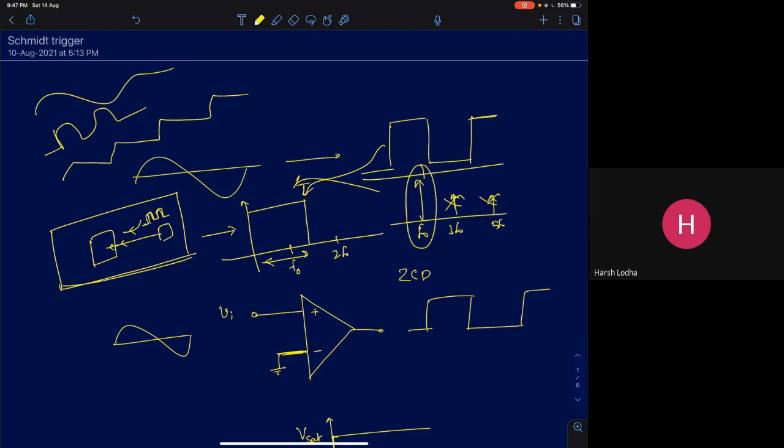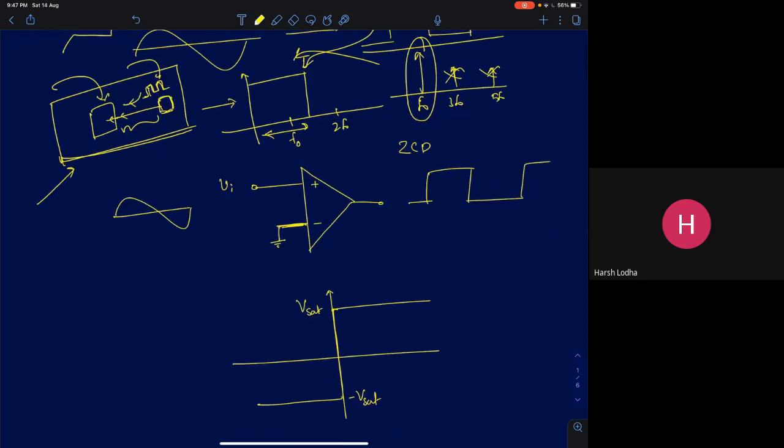The other, more common application is encountered in integrated circuits. Generally, you have a printed circuit board with copper wires for connectivity. For example, let's assume you have a digital processor on a printed circuit board, and a clock signal to that processor is coming externally. The dimensions of these wires will be on the order of a few centimeters. Even if you have a very good clock source generating a pure square wave, the copper wire is going to act like an RC circuit, which can be approximated as a low pass filter.